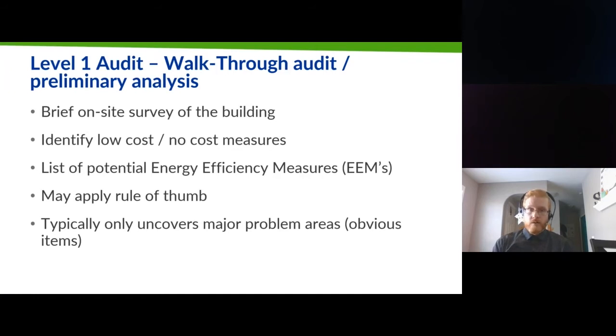So for this level of audit, as I said, it's a very simple audit. It's not sufficient for reaching a final decision on implementing proposed measures or EEMs, but it's adequate to prioritize energy efficiency projects and to assess the need for a more detailed audit. So, as nice as this sounds, it's a very basic audit.